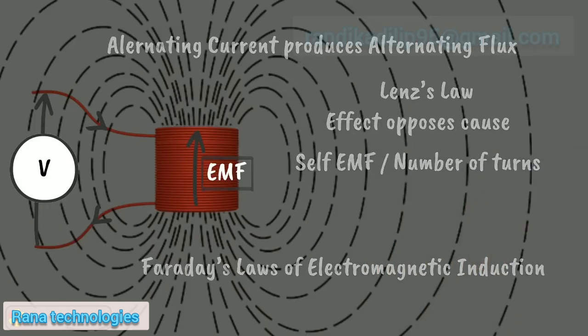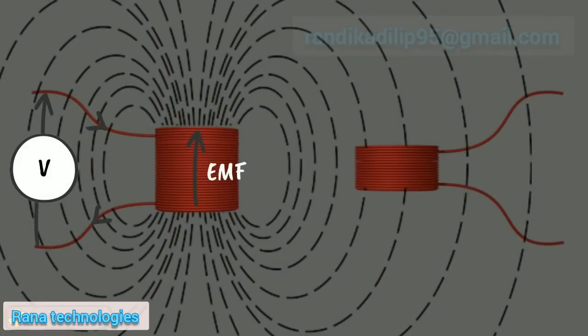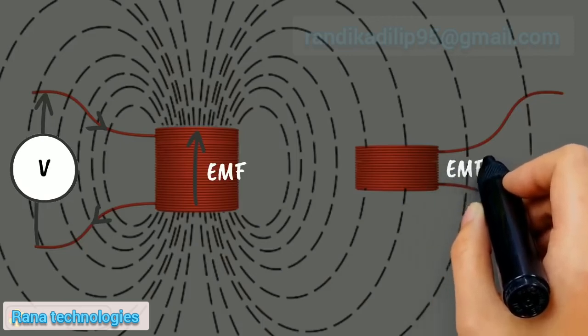We have said that there is another winding in the most basic transformer, but till now we have not discussed it. Now we are coming to the second winding in the transformer. Supposing one separate winding is brought nearer to the first winding, then this second winding gets linked with a portion of varying flux of the first winding. Due to this varying flux linkage, there will also be an induced EMF across it.